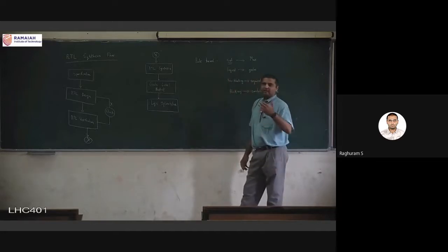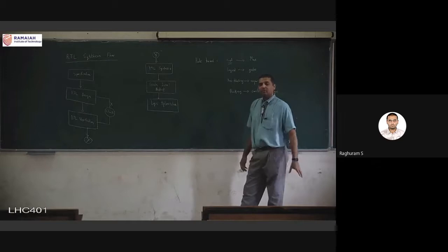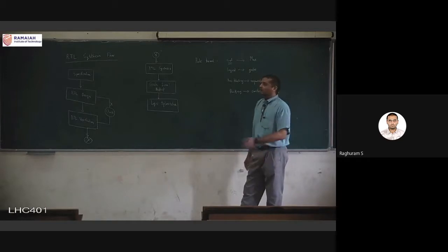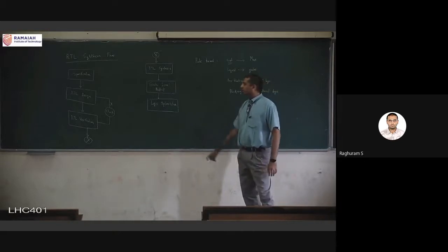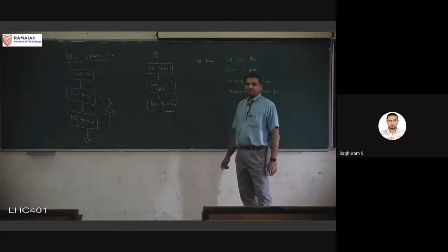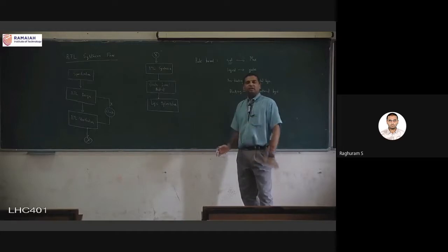One level higher than K-map, if you have, for example, 5 terms in the expression, then there is something called the Quine-McCluskey method, and there are other commercial logic optimization tools also. Many of them are open source. If you search, you will find them. But basically what happens here is, input is also a gate level description, gate level netlist. Output is also a gate level netlist.